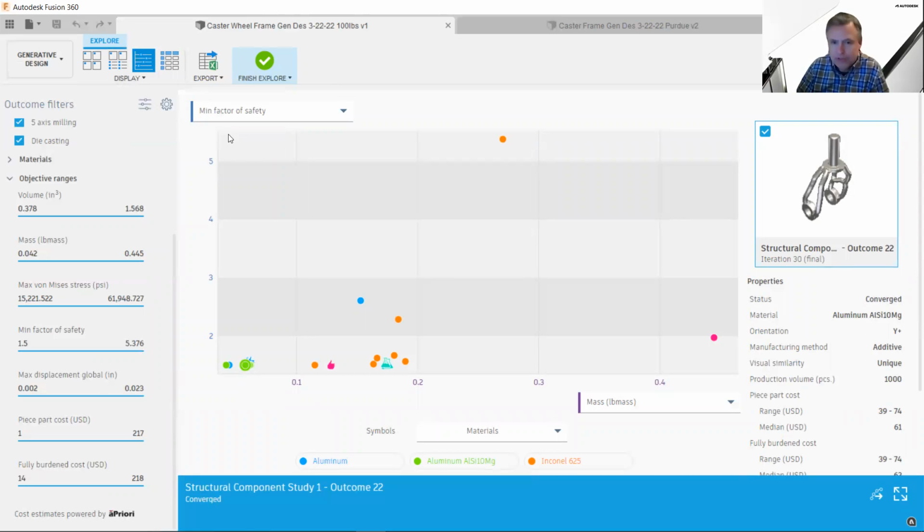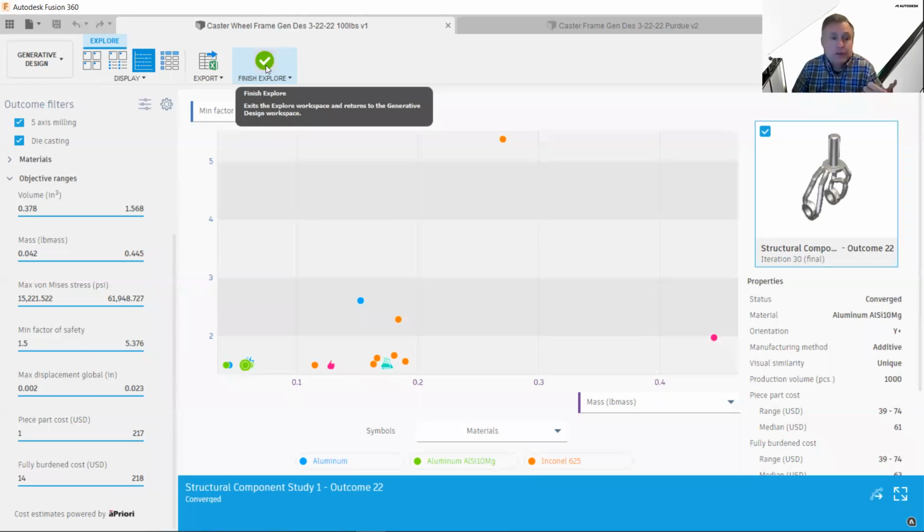As you're going through these different generative outcomes, don't be too surprised if you get the very first design outcomes back and say, I don't like them. I'm missing something. Maybe I don't have enough force, maybe there are really weak little sections in the middle. This is where you can go back and make changes: adjust the forces, add additional forces, change the manufacturing methods, and rerun it. We have found that people usually send up 3 different studies until you get your results.